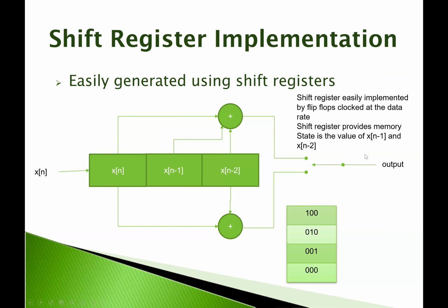This is the interleaver. So on one clock sample, we'll read from the P0 here, and then we'll switch and output the P1. This rate is going to be twice the rate as the data coming in. All right, and these are modulo 2 operations again.